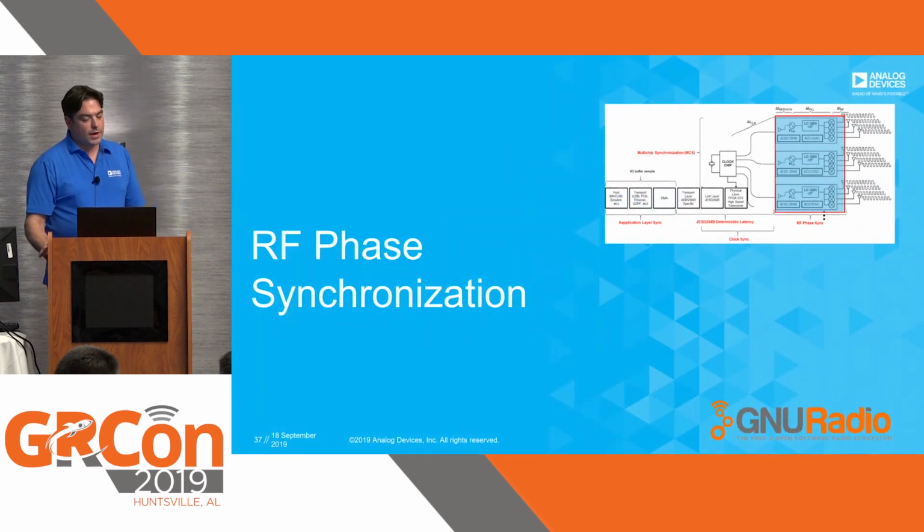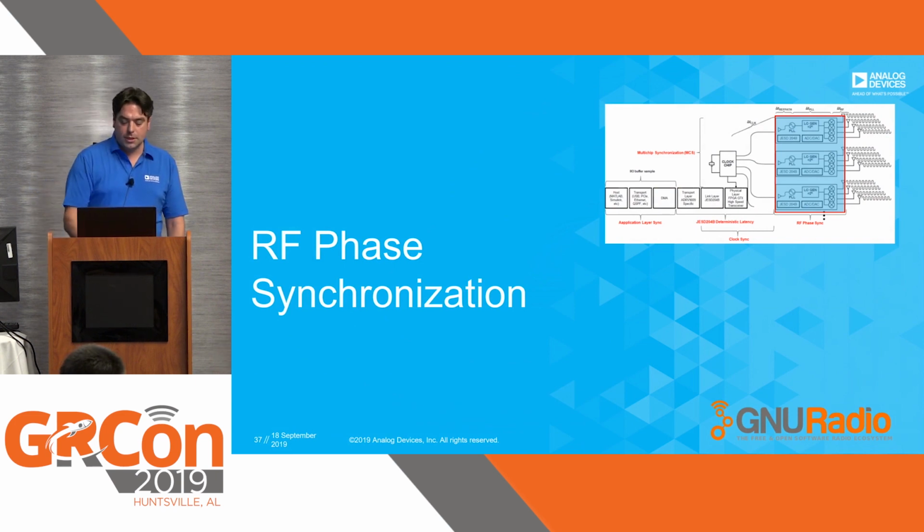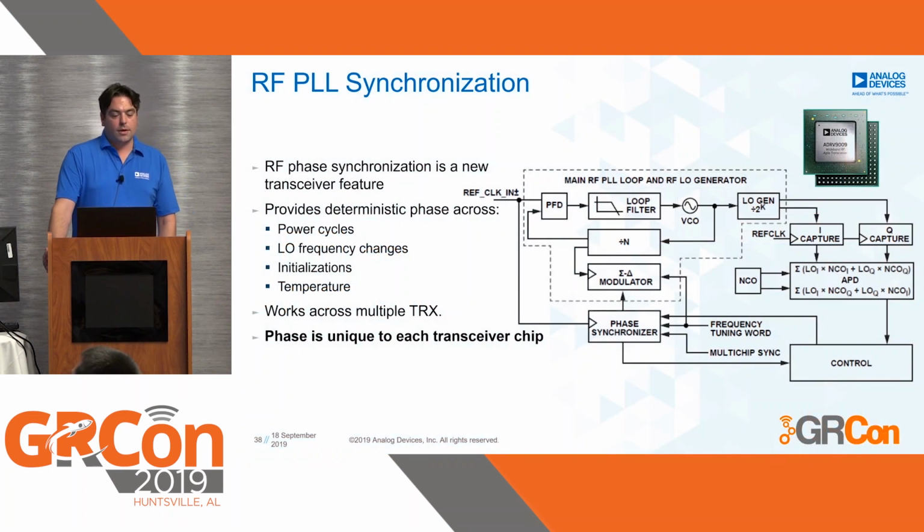So what is RF phase synchronization? Yesterday it was referred to as LO synchronization. The RF phase synchronization is a new feature on our latest generation of RF transceivers. It provides a deterministic phase across power cycles, LO frequency changes between initializations, as well as across temperature.